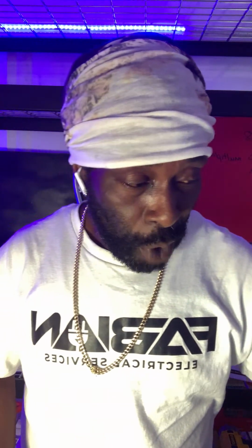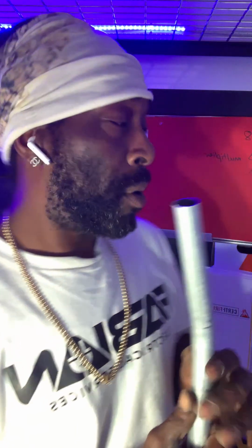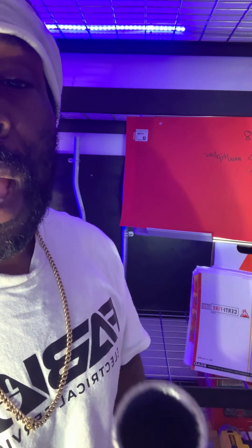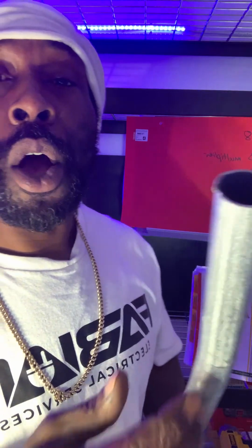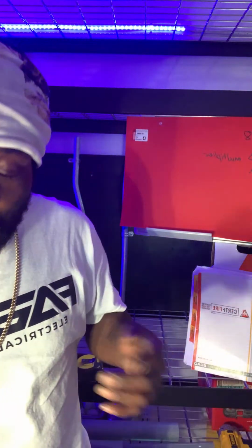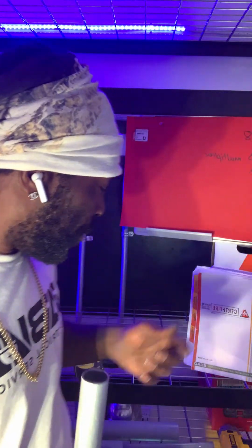Again, also when you are using EMT conduit, you have to be aware of this type of thing in here. As you can see, it needs to be reamed out. How we achieve reaming out our conduit is you can either ream it out with a reamer, but most guys who've been in the trade, like me, for 20 plus years, are going to use whatever we have on the job, whatever makes sense.